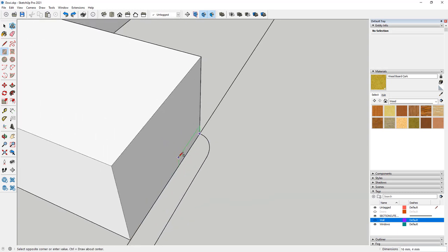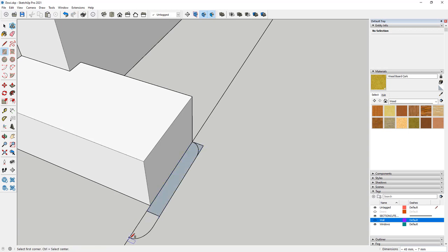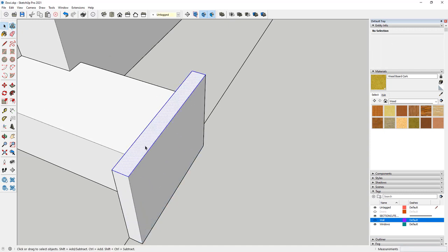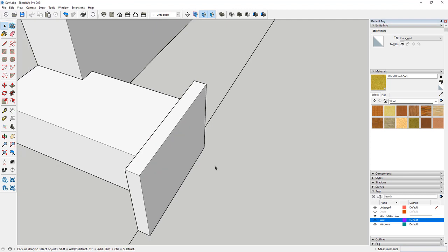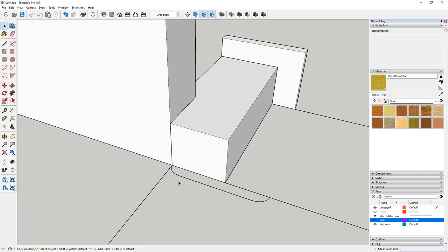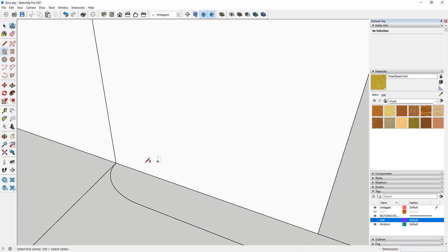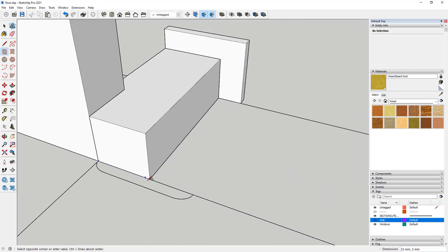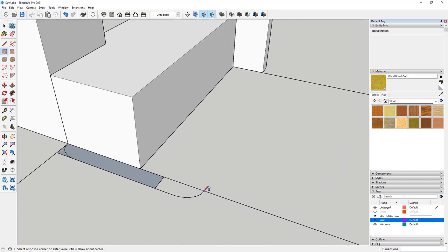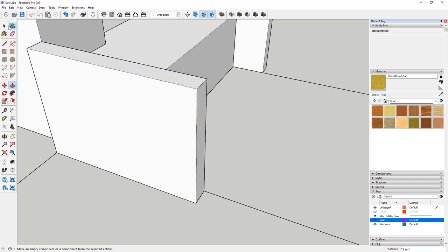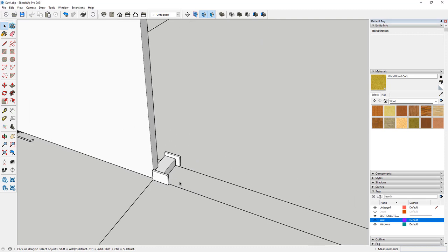And again, the elements that are outside, okay, and remove those from the inside. Then create them as components. The same from this side, also we need to create it in the same way. Remove thickness with the push-pull and create it as components. That's it.